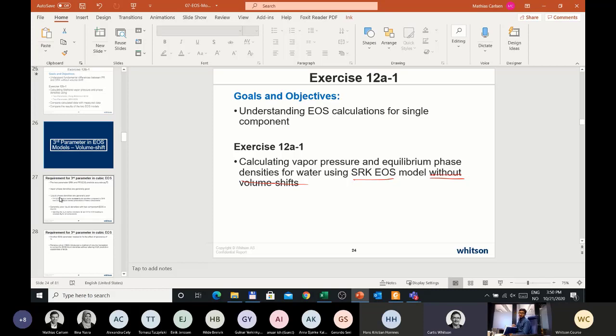Then Peng-Robinson came along and gave an equation of state that predicted better densities of oils, but still off by 10 to 20%. Instead of being off 20 to 40%, the SRK would predict stock tank oil densities maybe 20, 30% wrong. Stock tank oil densities with the Peng-Robinson were off maybe 10 to 15 to 20%. It was better, but it was far from being good enough.